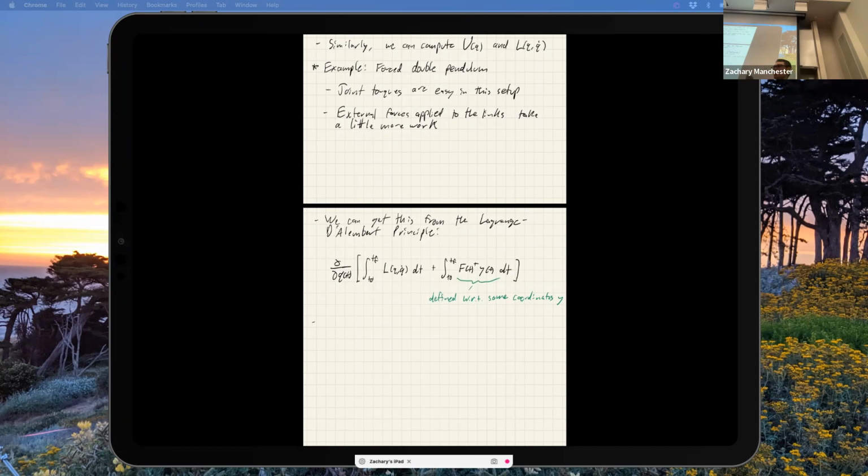So that's the idea. To make this work, I want to write this guy down in the world frame coordinates, right? Some force vector in the world frame poking at this thing somewhere. And so I have some other set of coordinates that I'm writing that force vector down in that isn't the joint coordinates. I can write that down however I want. Those are those other coordinates. And now when I take the derivative with respect to q of this whole thing, I chain rule through the y coordinates to get to the q coordinates, to get d/dq. So I'll write that down right now.